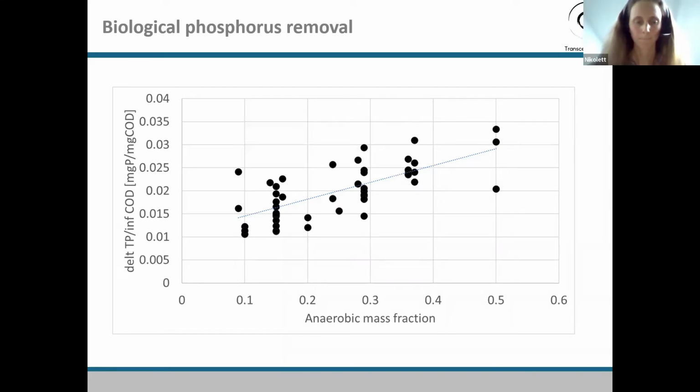Hey, Letty, we have one question in the chat. So Hung asks, how can we run dynamic simulation at a pre-design phase when dynamic data is not always available? Good question. Actually, we are generating this. If we are considering the temperature, that's typically always available, what the minimum and the maximum temperatures are. And the other part regarding the flow is, if you already have the information about the average flow and, for example, peak daily flows, so how the daily flow varies during one day, that could be entered.